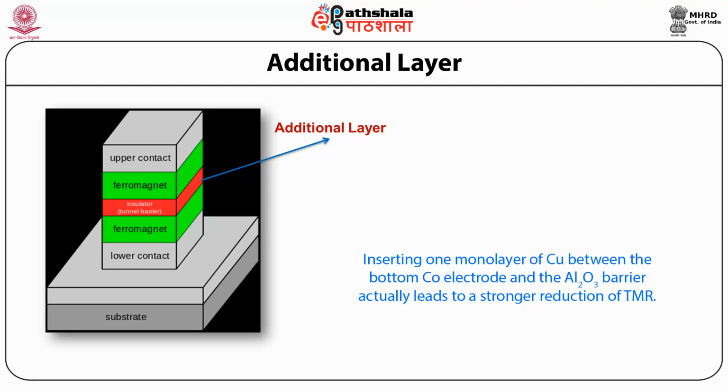Kaiser et al. found that the measured P is the sum of independent spin polarized tunneling currents from the cobalt and gadolinium subnetworks, resulting in a sign change of P with alloy composition when combined with traditional ferromagnetic material with positive P in an MTJ. This leads to positive or negative TMR depending on the sign of cobalt-gadolinium polarization.